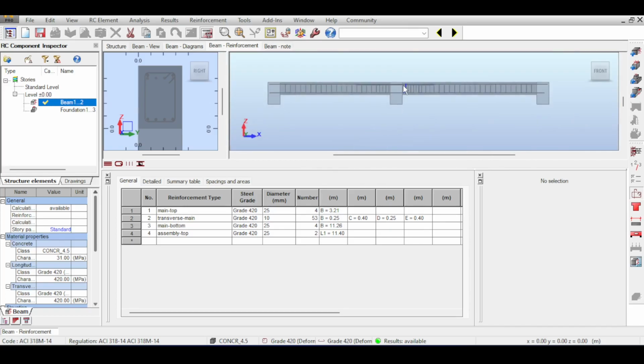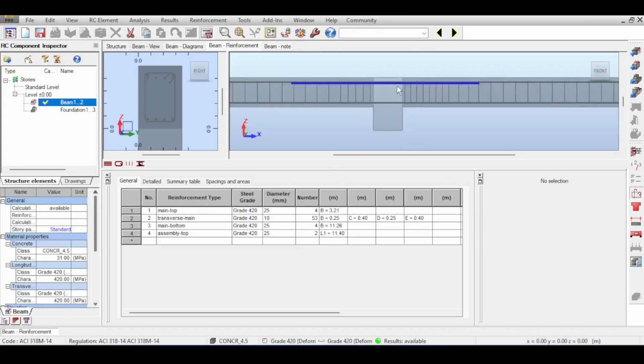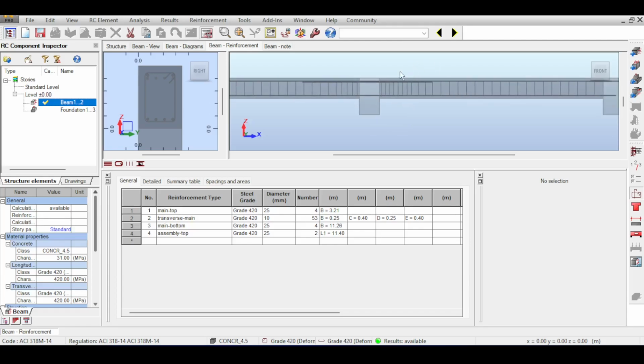Trust me, I have seen a lot of stirrups that cause confusion among the workers. So usually, and this is a personal opinion, I like my stirrups to be 5 centimeters spaced, like 50 millimeters, 100 millimeters, 150 millimeters, and so on. So I will change that.